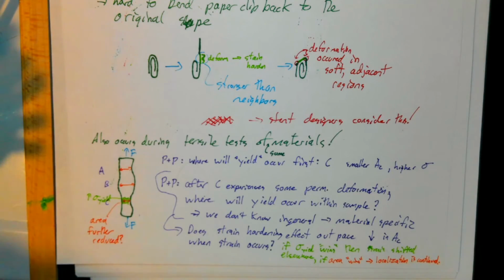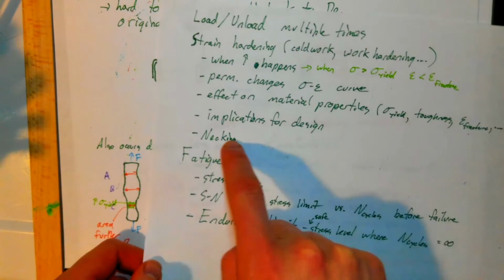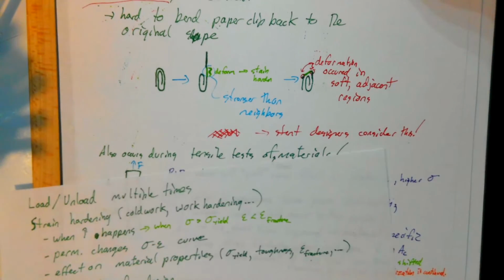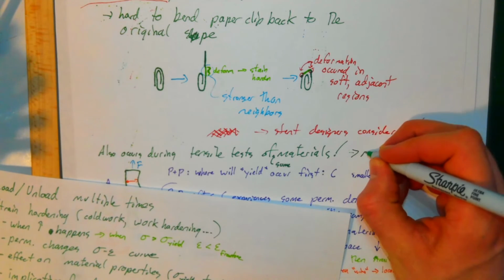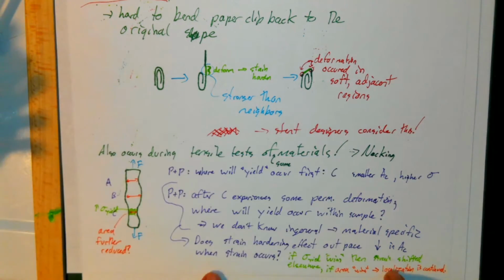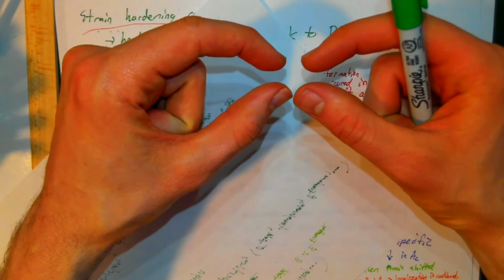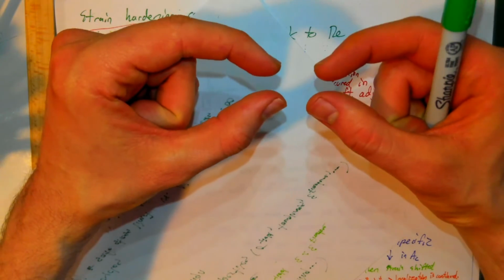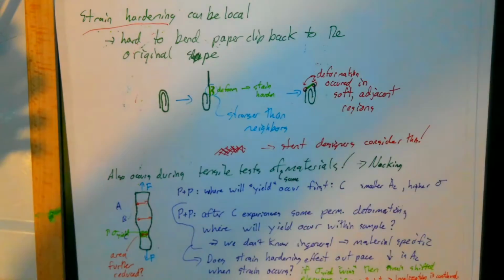So to tie things back to our thing here, what I'm talking about right here is basically this phenomenon called necking. And in particular, it's this last case, right, where the localization of strain into one region causes that material to neck down. It was originally wide, and then it necked down into this narrow region where all of the strain was focused.